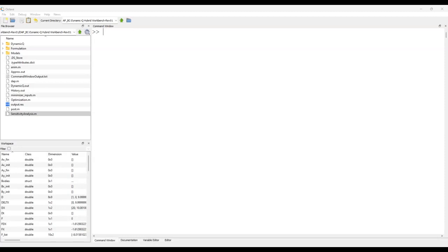So ideally what we want to do for a sensitivity analysis is choose a step size that is on the constant line that we have over here. That ensures that your optimization has stability within it. So for example, in this case, we choose 10 to the power of minus 8, which is fine.